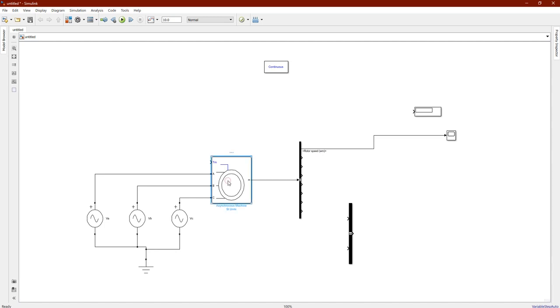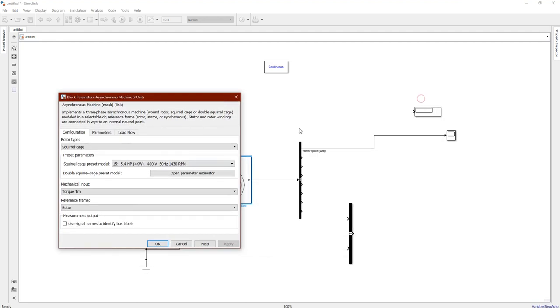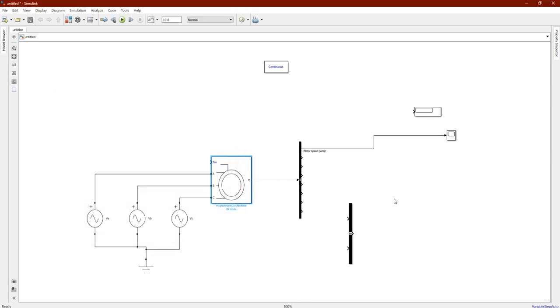If you see here that the speed is 1430 rpm, so I would like to change the radian per second to rpm. So how can I do this? Remember that the speed itself, omega, is equal to 2 pi n over 60. We explained this before. So in order to change from omega to n, we will multiply omega by 60 over 2 pi.